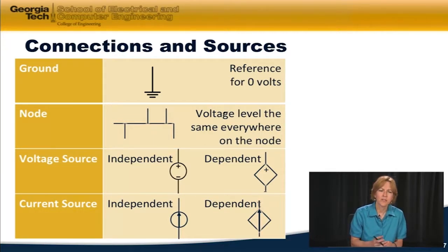Now, when we get to electronic circuits, it usually has a little bit more meaning to it because we oftentimes power these electronic circuits with AC or wall power. You know, you plug it into the wall. And when you plug it into the wall, we're connected to a power system. And that power system, the power that comes into your house, usually is grounded, meaning that there's a connection down to the ground, to the real ground, to earth. And so when the power supplies are connected to the wall, and then they're connected to your circuit, oftentimes we're required to ground our circuit. So in that case, the ground oftentimes has a more physical meaning to it, really relating to the true ground.